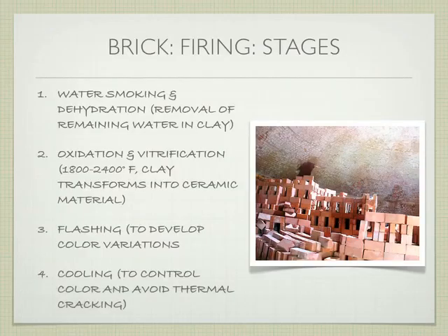Okay, so if we're talking about the firing, it goes through several stages, right? So the first stage of firing, this is that process of heating the bricks, right, and cooking the bricks, is what's called water smoking and dehydration, right? So we had, if it was the soft mud process, we had 20 to 30% moisture content. We need to get more of that moisture out, right? And if we were down in the stiff mud process, less moisture, so it takes a little bit less time to do this. We're removing as much of that water as possible, okay?